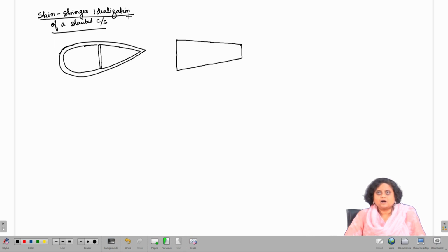We often encounter an aerofoil kind of shape. Many aircraft components have this aerofoil shape. Now, it is very difficult to approximate an aerofoil by a straight rectangular cross section. So, for that purpose, we can get a fair approximation of the aerofoil shape by a slanted trapezoidal kind of approximation. This therefore is going to be a simpler approximation of the aerofoil shape.